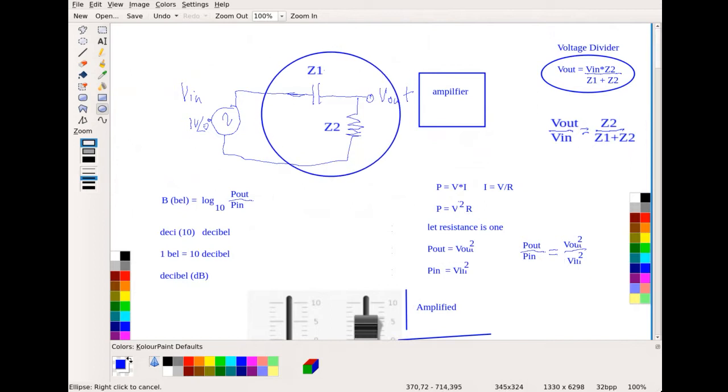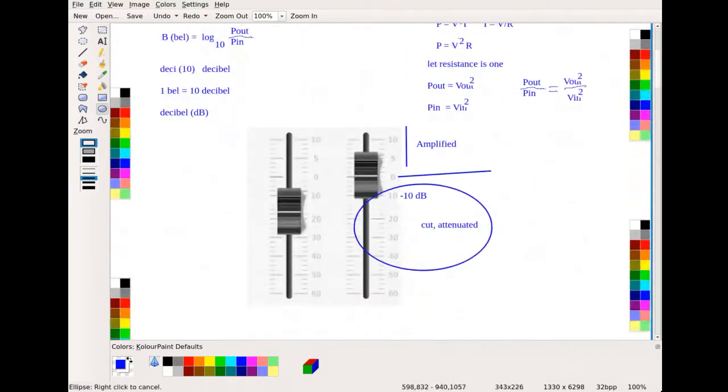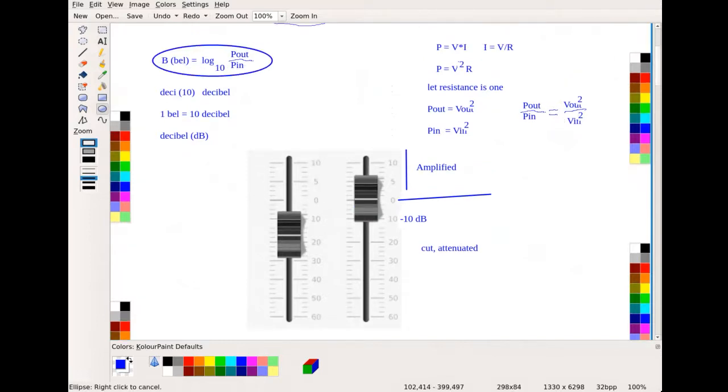I think I've used that term before in class where I've talked about passive. Capacitors, resistors, and inductors are all passive devices. They don't have any way to do any amplification, and so with just a filter like this, you're only going to be down below the 0. Now, wait a minute, why is that 0? Well, that goes back to this log equation over here.